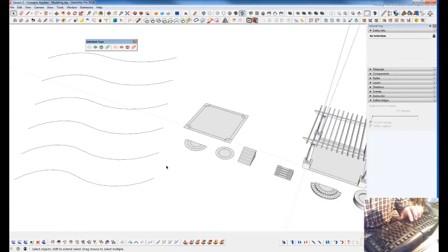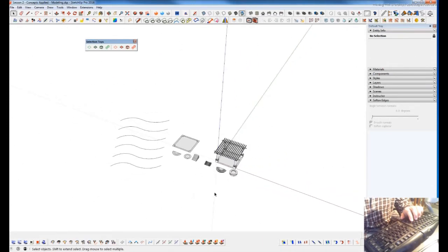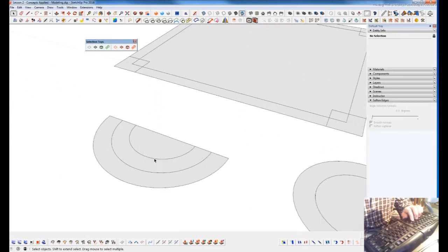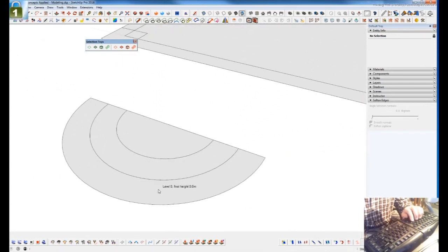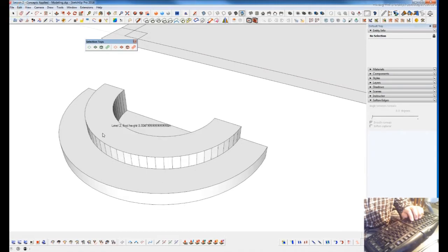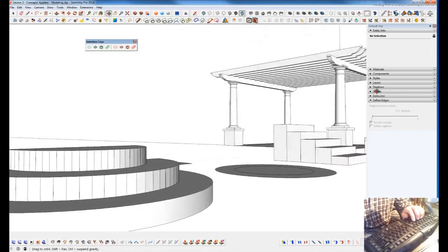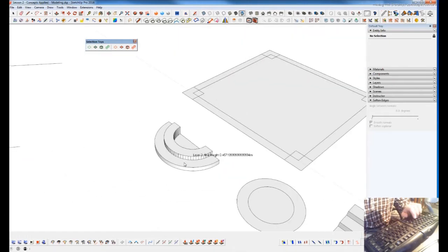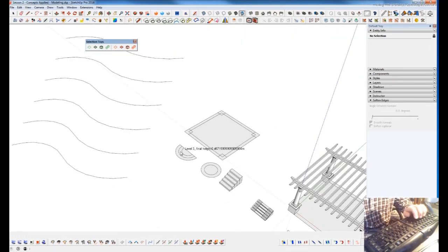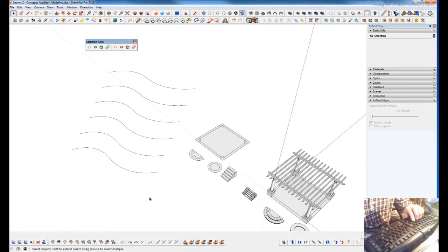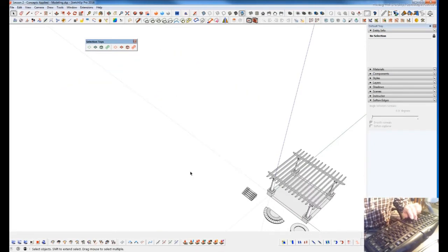So it will work from outside the group at the very top level. So we're at the very top. There's no groups selected. I can use the step extrude, set that to 6 inches, and I can actually click, and it'll go through inside of those nested groups, and that would work. So again, group-based workflow. It's one of those tools that's very helpful in those situations.